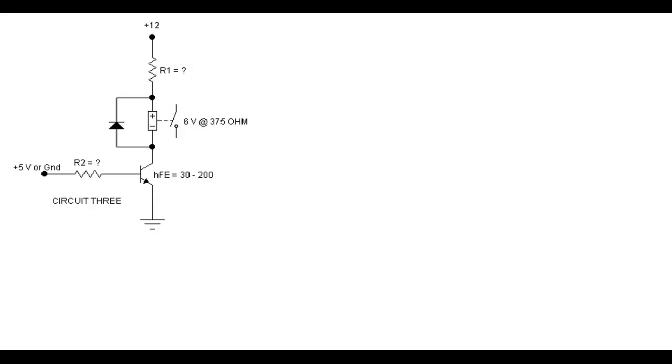So a relay has what we call a pull-in current, which is the minimum amount of current you can put through the relay that guarantees that it will generate a field big enough to pull it in. So undoubtedly, that's what I was looking at when I rounded down.